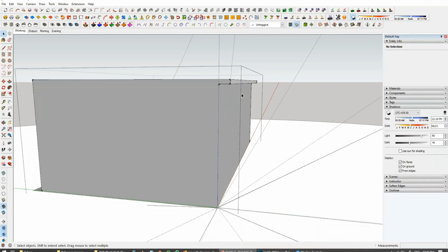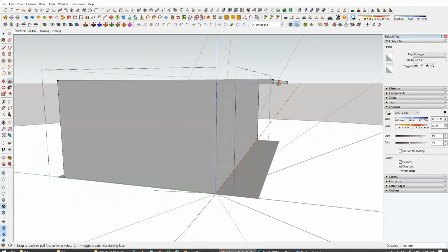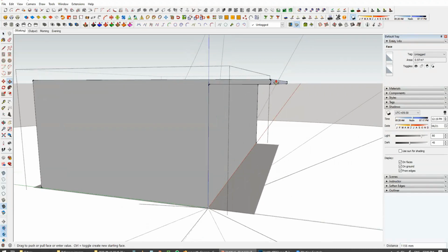So in India, normally we design it to prevent the sun from summer and allow the winter sun. So as a thumb rule, what we do is we prevent the sun throughout summer from the two equinoxes. Okay, so let's draw the projection up to the equinox line.